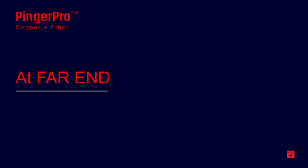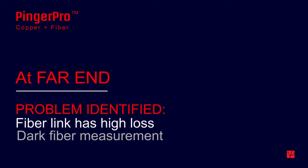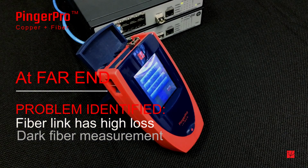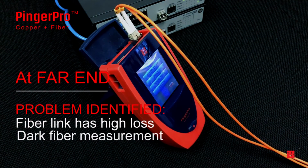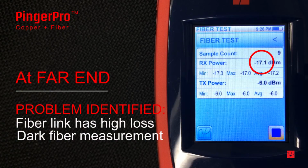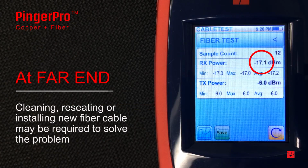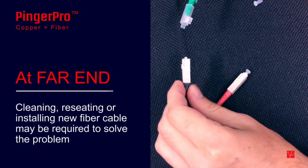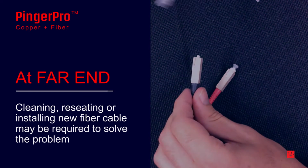We now know that the fiber link must be the cause of the large attenuation loss, and we can make a dark fiber measurement on the link by attaching the PingerPro to the disconnected fiber and measuring the transmitted and received power that is sent out and looped back. In this case, we see 11.1 dB difference and have verified that there is a problem in the link. Cleaning and reseating the connection points or installing a new fiber cable may be required to solve the loss problem.